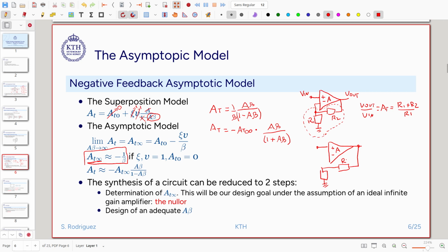In this particular case the amplifier is ideal, so we don't introduce many errors, but in practice it is not really easy to do. Put Vx here, and then we have V in, we have V out here, and then we can calculate our beta here, or we can calculate here a beta as the whole gain in the loop. So that will be the gain in this loop.